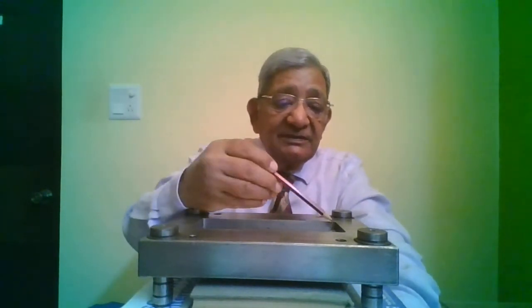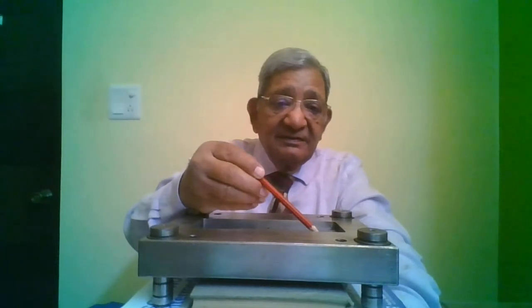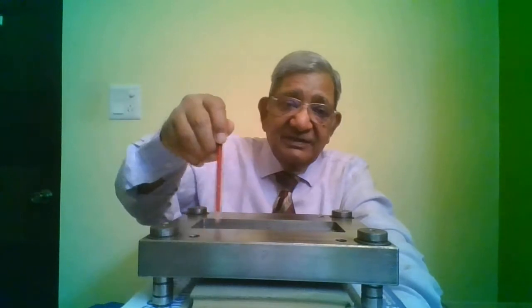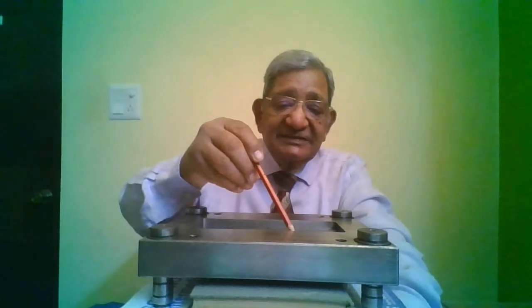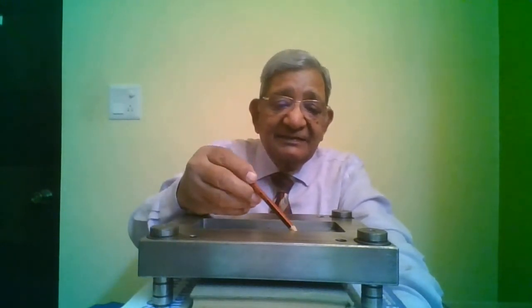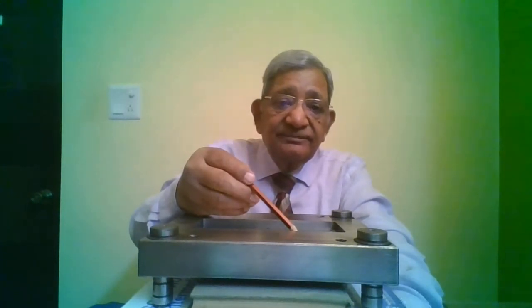Now the tolerance on the pocket width, that is, this is the width, here it is H7. Here also, lengthwise, the tolerance is capital H7. Now these inserts have got the tolerance of K6 on the width, and the length is maintained in the assembly.